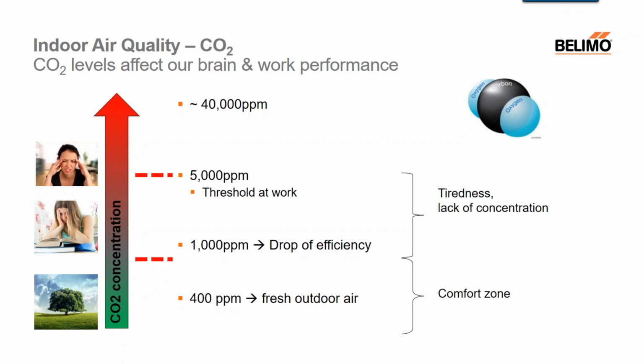Poor concentration results in loss of attention, increased heart rate, and slight nausea. 5,000 parts per million in most jurisdictions is the workplace exposure limit given in any 8-hour period. And above 40,000 parts per million, exposure to CO2 may lead to serious oxygen deprivation, resulting in permanent brain damage, comas, even fatality.